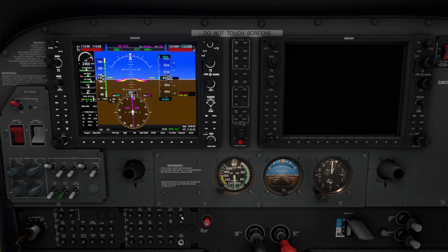And then we have the standby batteries still powered. And you can see over here, earlier we were discharging the main battery. That is no longer discharging because it has 0 volts because we turned it off, or we're simulating a failure. And we have 24.3 volts on the emergency battery, and you can see that is also showing a discharge of -6 right now.